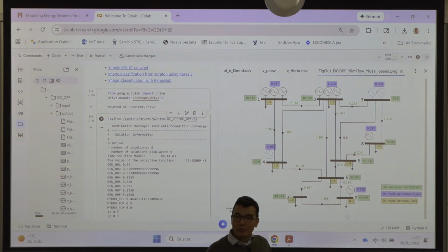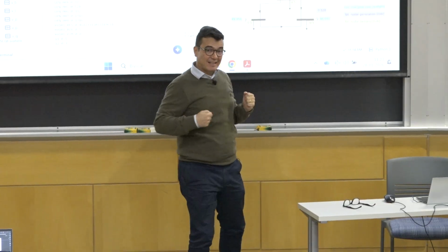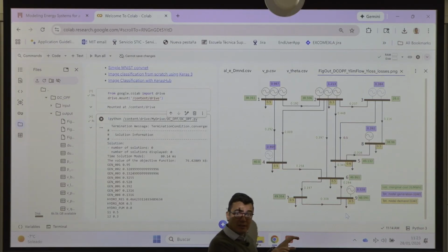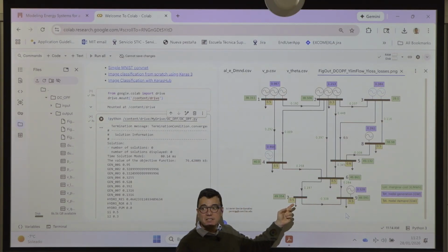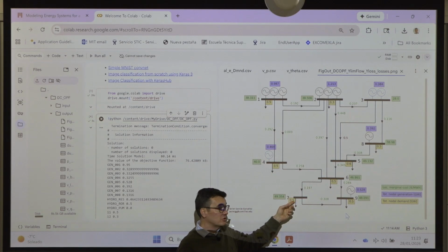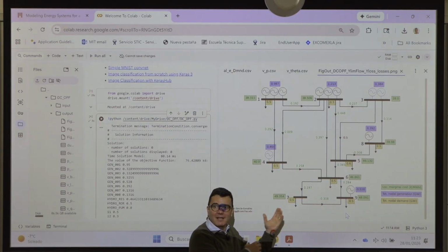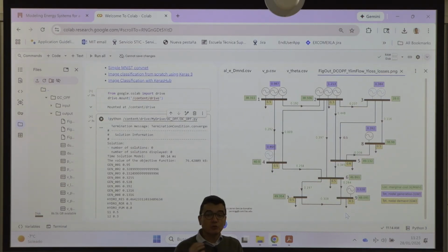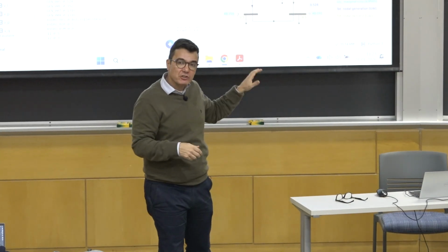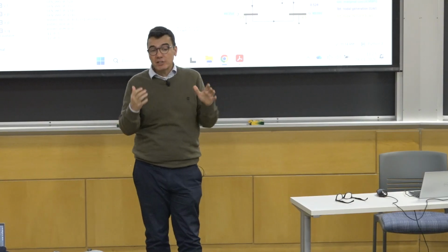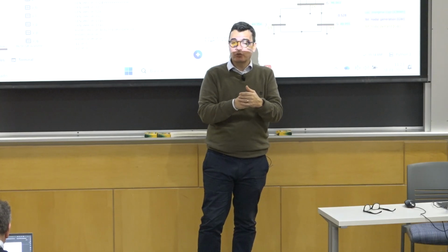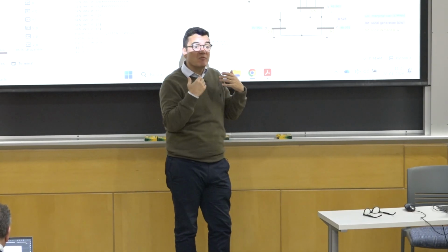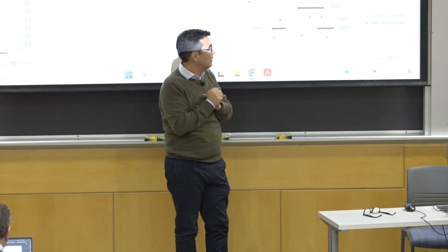So they provide the right incentives for connecting additional competitive generation, with lower price. If you connect here a very expensive generator, you are not going to change anything. But if you install here a cheaper generator, you're going to displace this expensive power here. And therefore, it provides a good economic signal to lead optimal investment. So locational marginal prices is not only an operational issue to determine how much I should pay to the generators or how much I should charge to the consumers, but also it provides a good investment signal to the system.